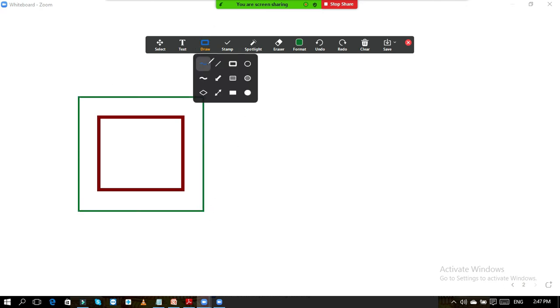Now we will draw the bars which are inside. 8 bars we have provided. This is one. I will provide first 4 bars at the 4 corners. So the placing of bars we will decide. 2, 3 and 4. So these are the 4 bars of 25 mm diameter. Then here at the center I will provide 1 bar, 5.